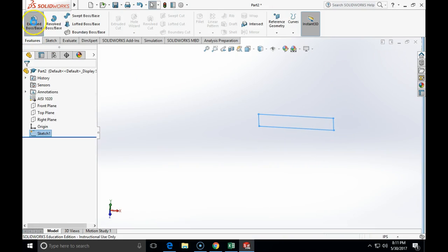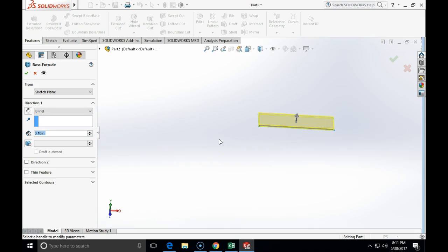Now I'm going to extrude this up according to a drawing, so that's the one end. Let's check back what is the proper dimensions here. Okay, so I'm going to extrude it for a 1 3/8 up to here, plus 1.18 divided by 2. Okay, so let's do this.